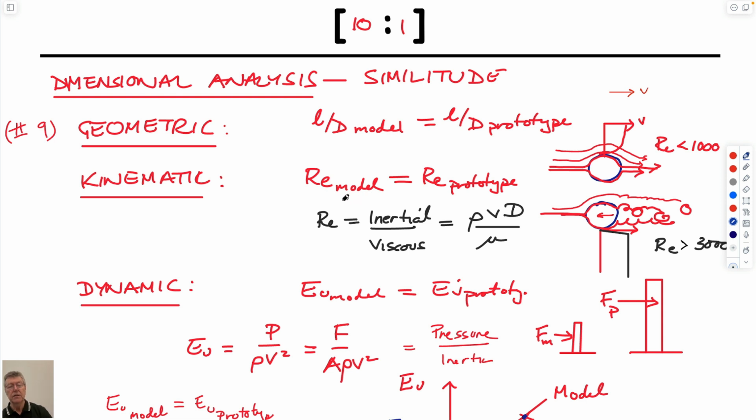And then you put it in the wind tunnel, and you want the regime that's flowing around it to be exactly the same as the flow regime that it experiences in real life. And so the flow regimes have to match. And if you take a golf ball or a hailstone or a cylinder which you flow fluids around, you'd find that if you have very slow flow, you get a kind of creeping flow. So the streak lines that you'd get would hug the shape and come off the other side.